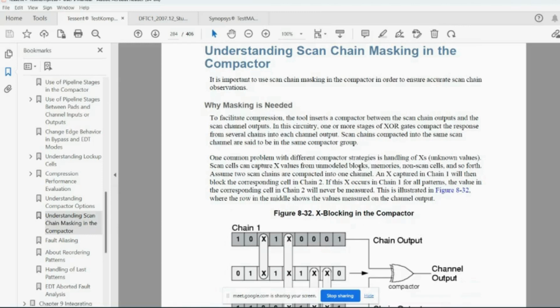That means certain OCC memories, any additional clock generator circuits or any other cells that we don't want to make part of DFT logic, and we don't want to convert them into scannable flops. So we make them non-scan by default.